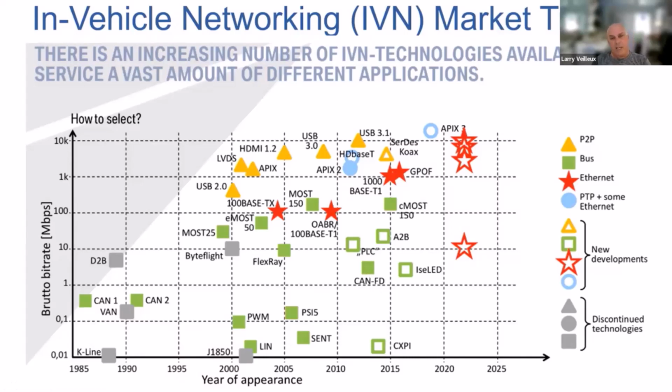And another big thing, which I'm not going to be discussing here, and which really hasn't seen a big implementation yet in the industry, is Ethernet. Automotive Ethernet, as they refer to it now, to a certain extent operates the same as Ethernet in your enterprise and those types of networks, but with a slightly different implementation. Again, I'm not going to be going over that, and there are reasons why we'll also introduce Ethernet into automobiles. So really today, most cars are a hybrid of multiple networking technologies, depending on the systems that they're servicing. I'll also mention LIN. And I have another slide that's going to cover some of these more common ones, similarities and differences.